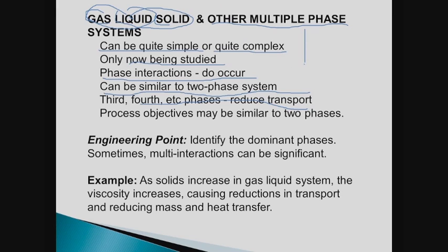When I deal with multi-phases, I would recommend thinking of it this way. Suppose I had a gas, liquid, and solid. First thing I'd want to do is have an impeller on the tank bottom, and that would primarily handle the solid suspension aspects of the operation. Then I would come in with my Smith impeller in the middle here, and maybe another Smith impeller here, and then I would sparge to both of those.